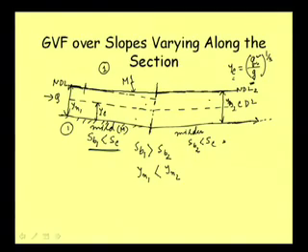Now, if we talk about computation of this profile, if we recall our earlier discussion on the M1 profile, we know that at upstream it will be nearly equal to the uniform flow depth, and at downstream it will be governed by the control section. Here the channel reach is fixed and this depth is known to us.